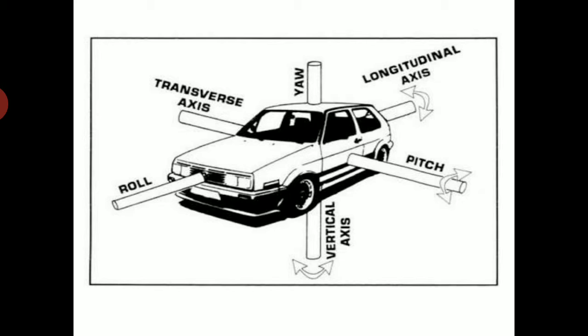The center of gravity of the vehicle will be at a certain height above the ground level. So the turning couple about the longitudinal axis of the vehicle will be induced during cornering. While turning, cornering force will be there because of the centrifugal force acting at the center of gravity and forces at the tire road contact surface. This results in a motion called rolling. This is how the rolling takes place. This causes the left hand suspension to move out of phase with the right hand suspension.